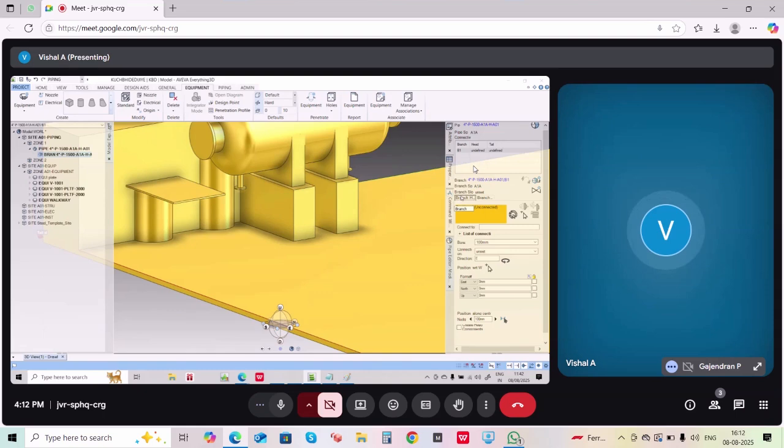Today I'm just giving you an example of how the pipe is created. Then we will discuss piping in detail, all these tools. So I select branch head. Now click on this cursor and click on the nozzle. Automatically your head starts from here. Once your head starts, the pipe will automatically fetch the details of the nozzle, the size and the rating. That means 4 inch and 150 rating, and this piping spec is also from 150 class, so whatever component comes will come from 150 only.